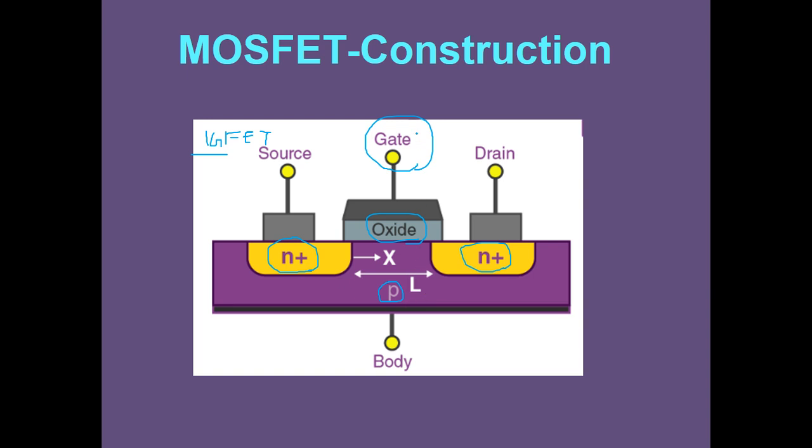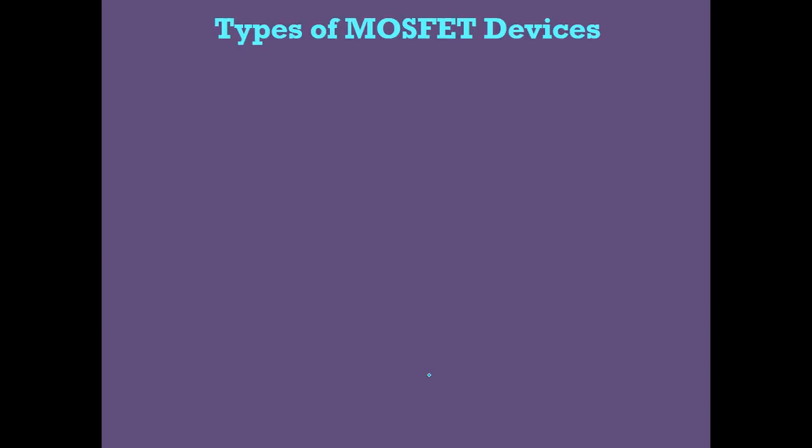That is, in between the gate and substrate, we have kept an oxide layer, also called a dielectric layer or an insulator, that is, an SiO2 layer. Over the SiO2, metallization is made in order to make the gate terminal, right? We don't want any such insulation in the case of the source and the drain. Therefore, the oxide layer is etched out in these N plus wells, and a metallic contact is made for the source and drain. One more terminal is called bulk or body or substrate.